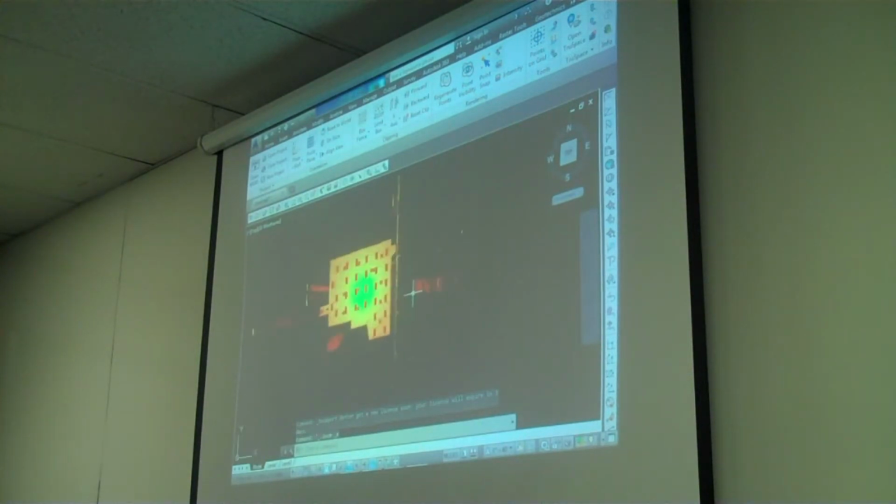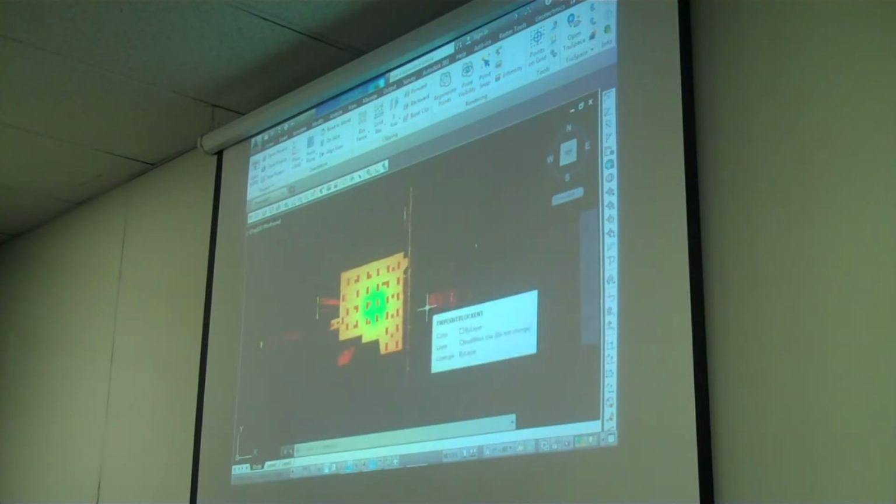All right, so this is the Holman storefront and the interior. Two different scans. Tommy did this from the outside. Tommy did this from the center. You'll notice down here, it's already in state plane coordinates because he used the GPS to set up the total station outside, and then he used the total station outside to get himself inside. So here's that opportunity that I was showing you in the field to work with the GPS on top, the GPS alongside, and then have some relevance to this building data as you're starting to bring it together.